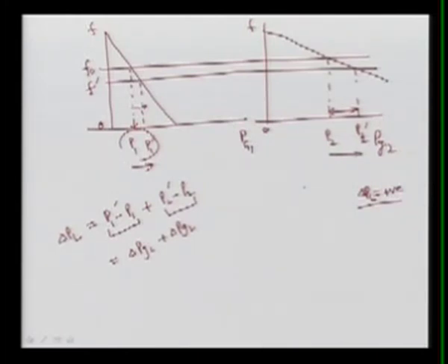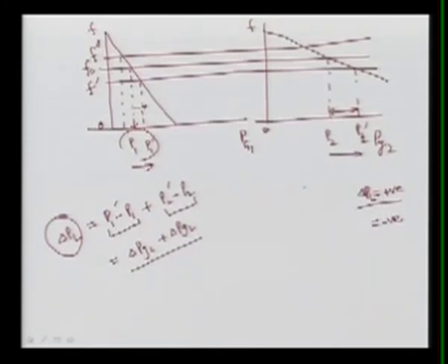So this is the load, if it is increased, this is the value they have to go for. If reduced, we can also see what will happen if this is negative. Means we have reduced the load, what will happen? System frequency will go up, and you can see here f double prime. Now we are getting P1 double prime and P2 double prime. So we have shifted, means we have reduced the loading, and you can see that the reduction of load in the two cases is much higher than in this case.